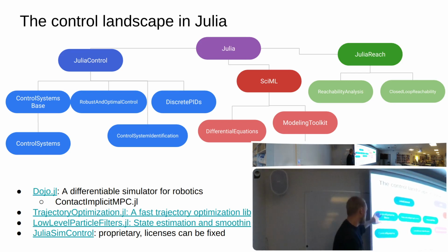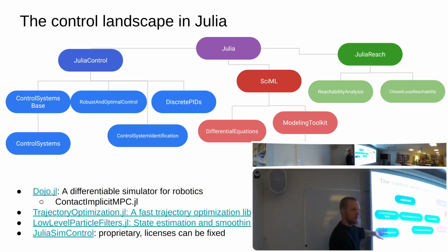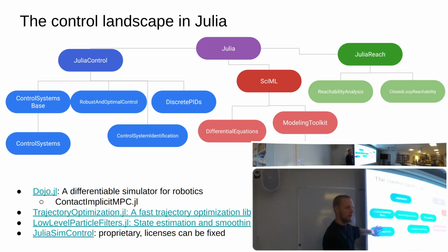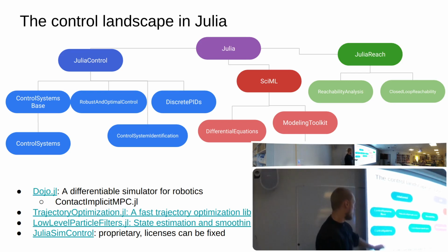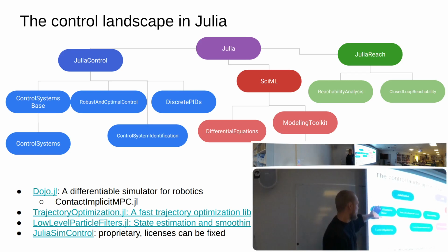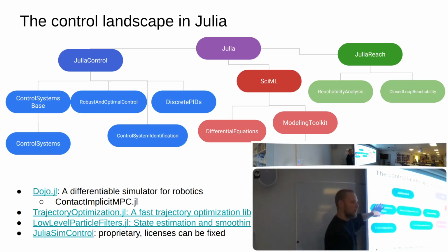The only difference here is that this full package, if you use this, you have access to continuous time simulation. So if you call LSIM or STEP with a continuous time system, that will be simulated in continuous time if you use this. If you use this package, you can still simulate stuff, but in discrete time then. And all Bode plots and frequency domain stuff, and that is here. So very often you can just make use of this.